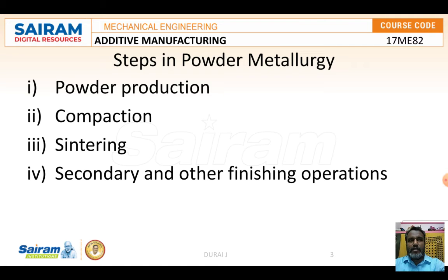Several production methods are available for making powders, such as crushing. Mainly the atomization method is used, and around 80 percent of powder materials are made by this method. It produces both ferrous and non-ferrous metals. Special powders like stainless steel, superalloys and titanium alloy powders are also made with atomization techniques.